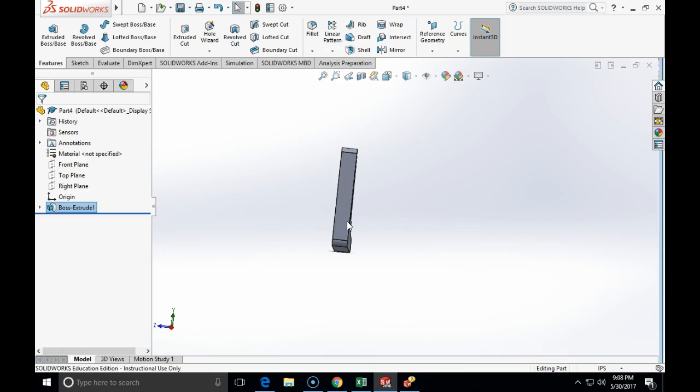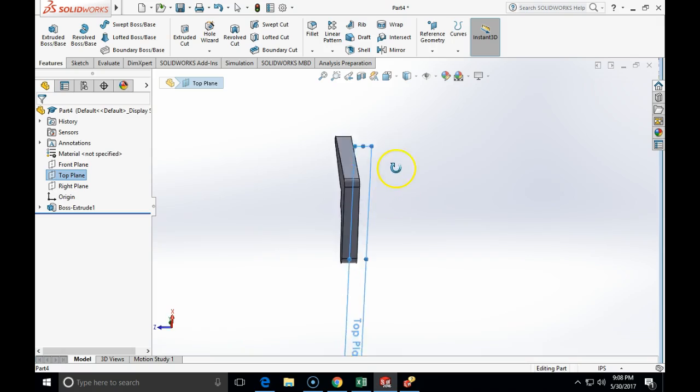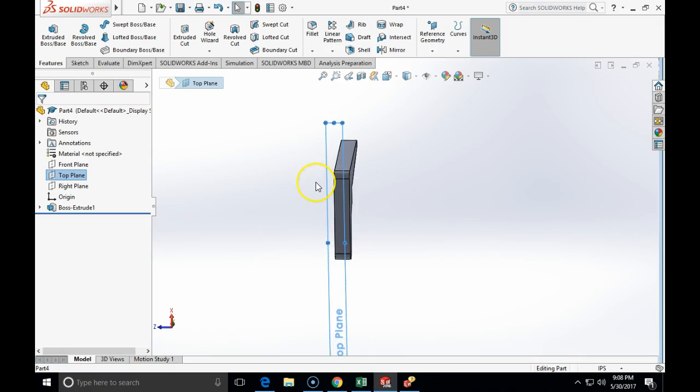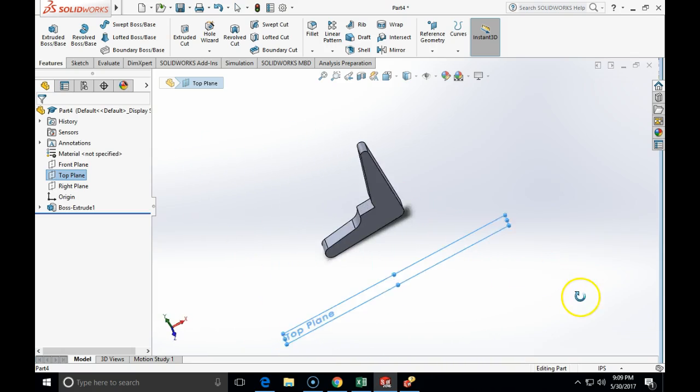Now if I want to do, let's say, another projection, I will choose the front plane, or I will choose, for example, a top plane, and make another picture in the top plane, do the same dimensional scaling, and then align some of the lines which are visible from the current structure I built, with some line, edge, point or vertex of what is visible in the other projection picture. That way you can kind of build a glass box and reconstruct the item in a glass box.